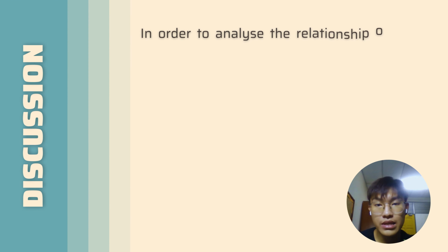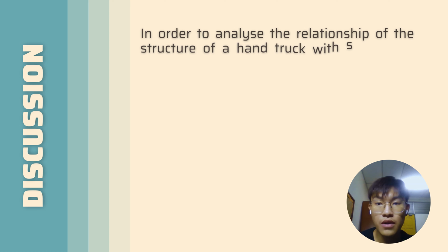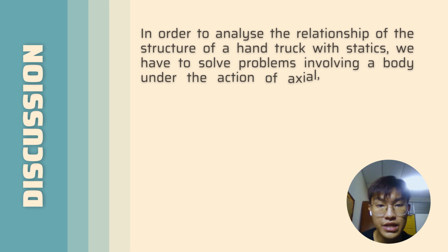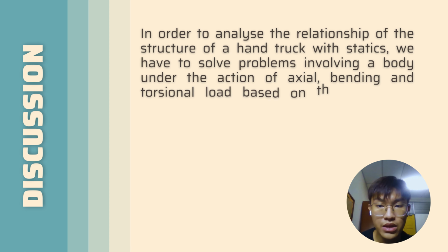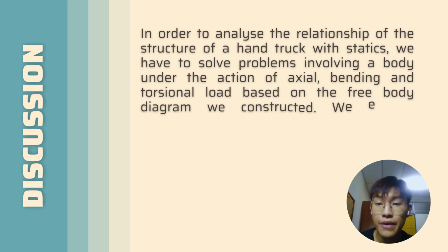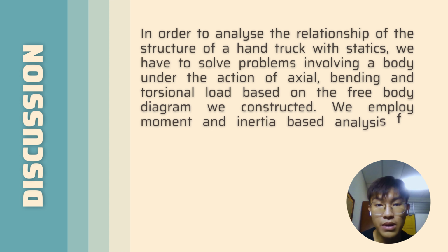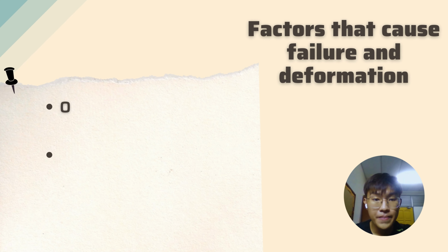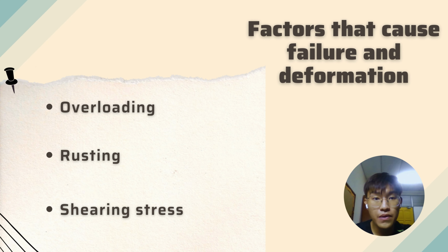In order to analyze the relationship of the structure of a hand truck with statics, we have solved various problems such as the action of axial, bending, and torsional load based on the free body diagram that we have constructed. We also employ moment of inertia based on the analysis for problem solving due to the compound loads. Based on our observation, there are a few factors that cause failure and deformation. The first one is overloading, next rusting, and lastly shearing stress force.